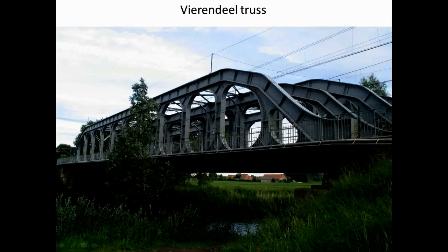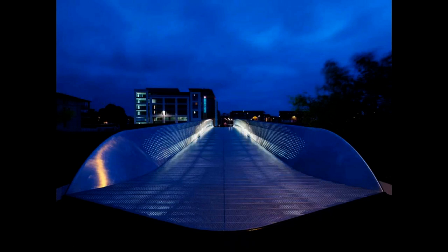But they also did something very clever, which was, I'm sorry you can't quite see it here, that they analysed how many perforations they could put in according to the structural loading that the bridge would have to endure. So as you can see, as we get down to the end here, it's actually losing its perforations, because here they needed a more solid and continuous form because all the load is coming back at these points. So they did what's known as a finite element analysis on the bridge, which I will show you at some later stage.